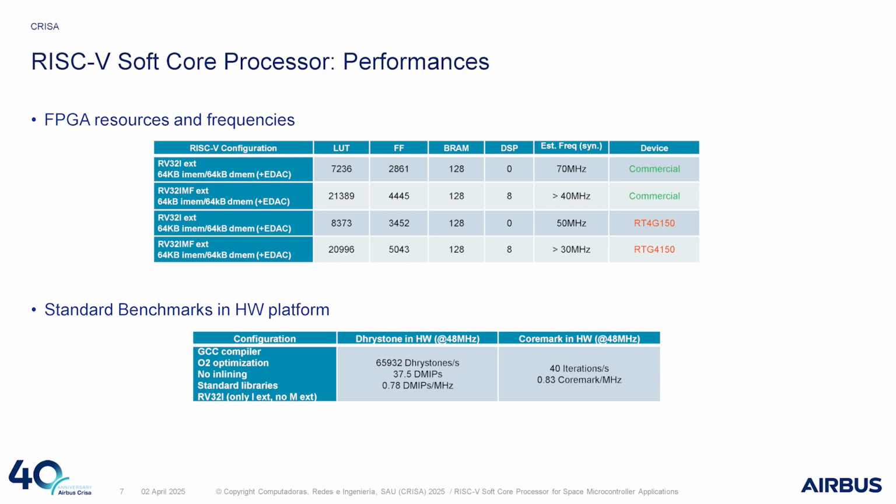When we include the floating point operations, basically we have about 1,200 flip-flops more due to the register file that requires the F extension. Frequency is not that high, but this figure is already updated. We are reaching higher than 65 megahertz, which is a matter of updating or configuring well the multi-cycle constraints in the synthesis and layout tool, or getting rid of some hazards in the pipe.